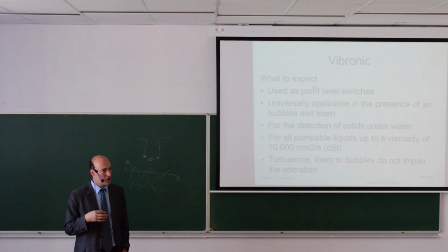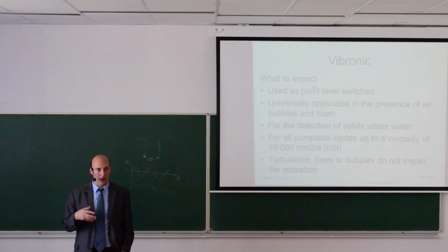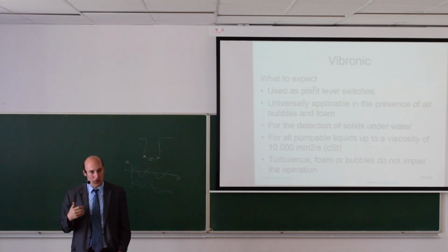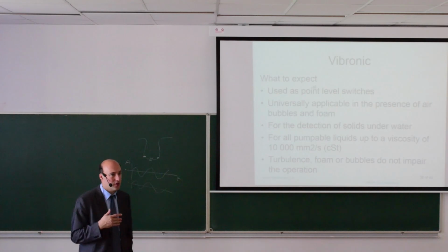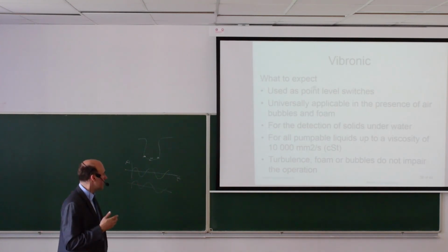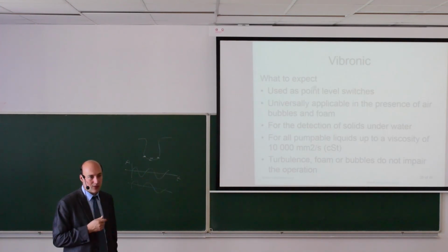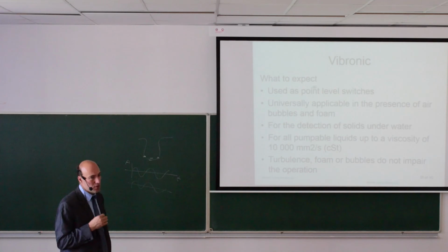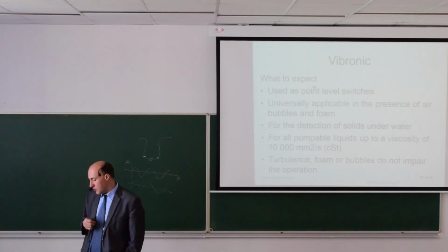So if you have a mixture of water and sand, for example, as is typical for the water treatment industry, then you may detect sediments on the bottom of the tank and clean it from time to time. It is for all pumpable liquids up to this high viscosity, and we don't have trouble with turbulence, with foam, and with bubbles.